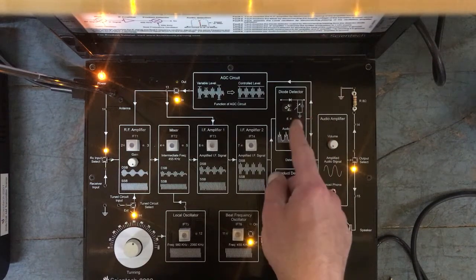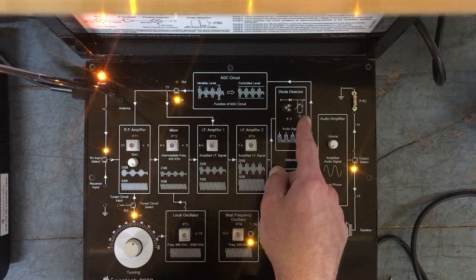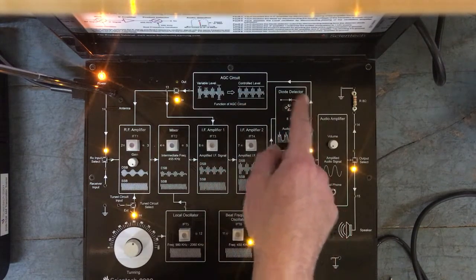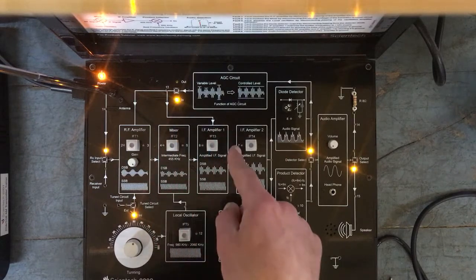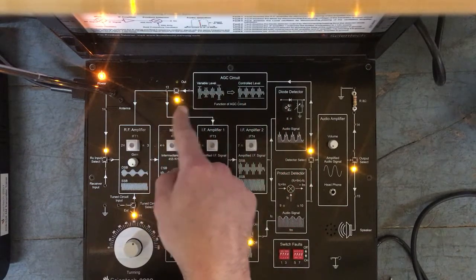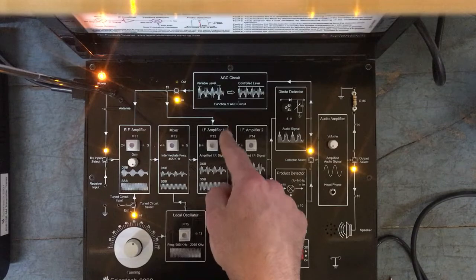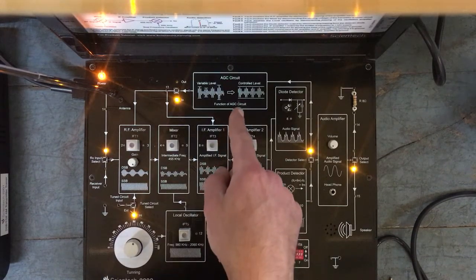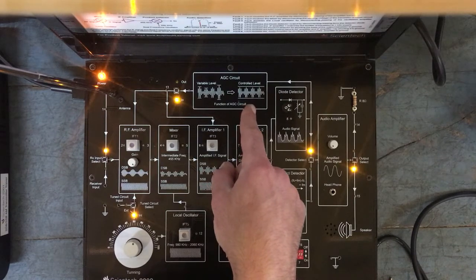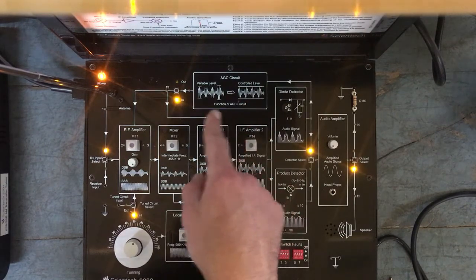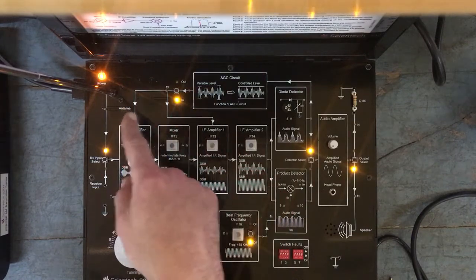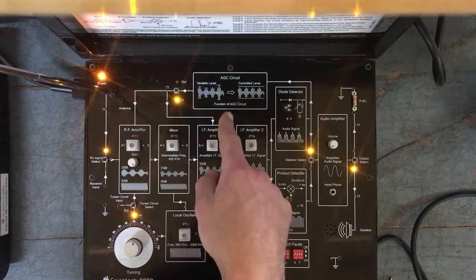And we have activated the automatic gain control circuit as a feedback, as you can see in this case, which actually changes the gain of this first IF amplifier, which would compensate for certain increases in the input voltage level if our transmitting signal is too close.